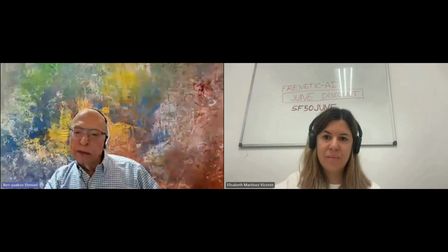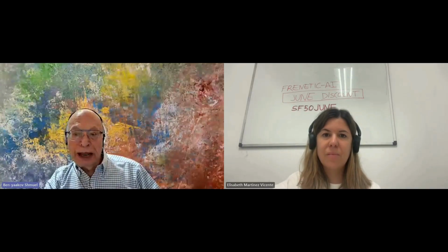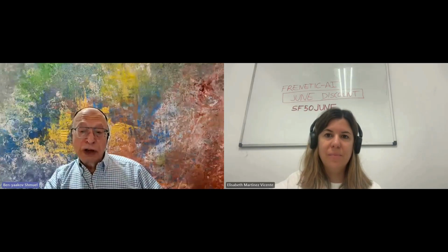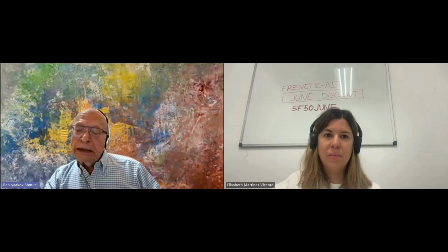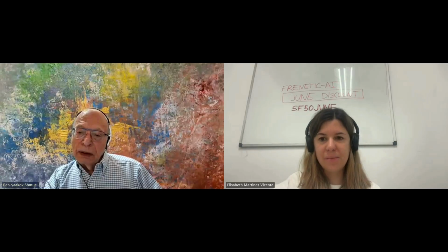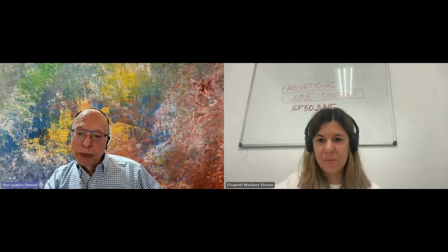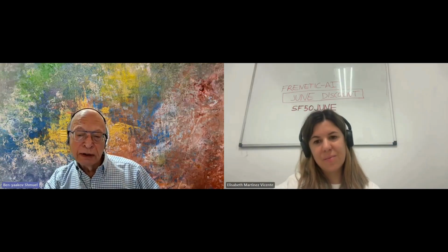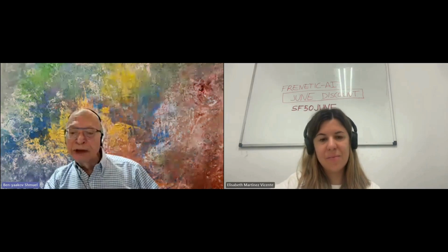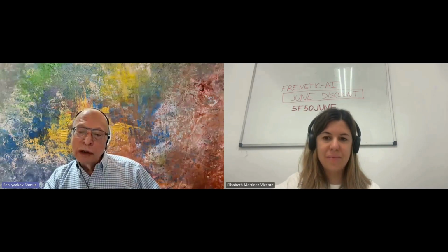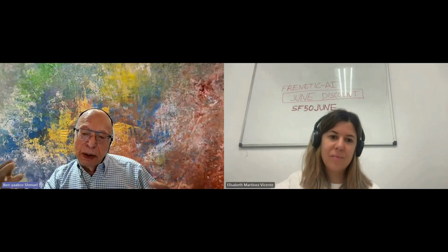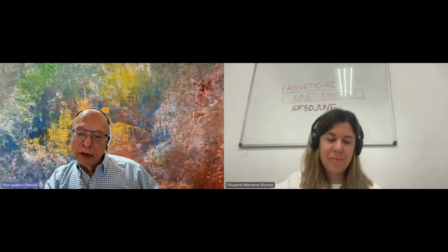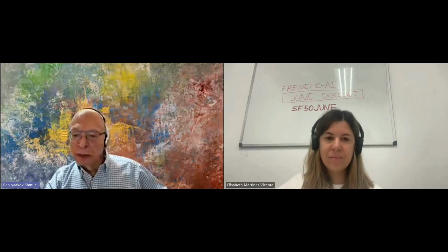The question of, for example, magnetization: do you mean the actual magnetization of the core or what you see in an equivalent circuit? Obviously, to mimic what you see from the ports, there is a relationship between the leakage and the magnetization. But as I've said, it's not one unique answer. You can have different magnetization models that mimic or give you the behavior of a given physical transformer.